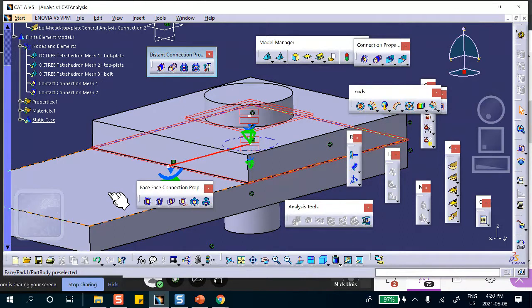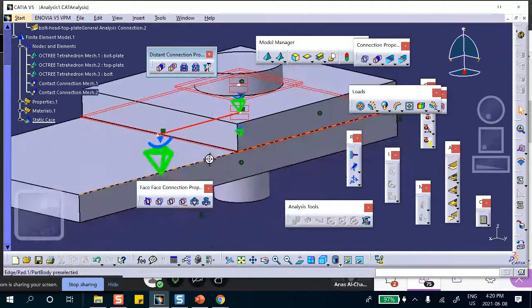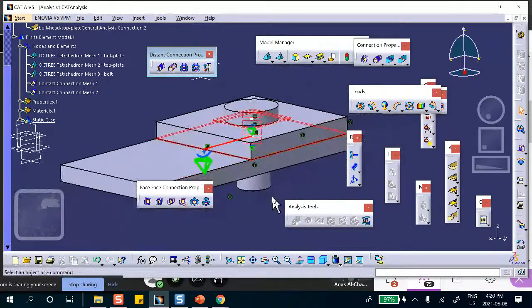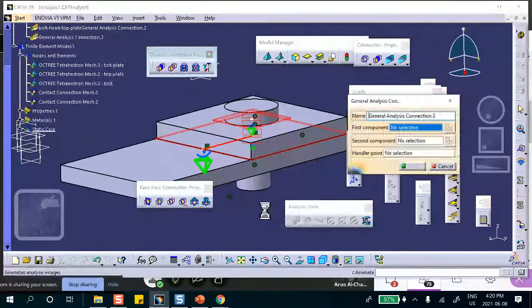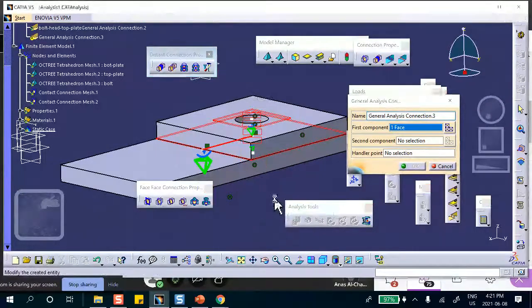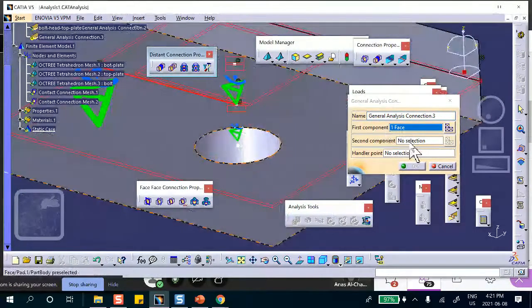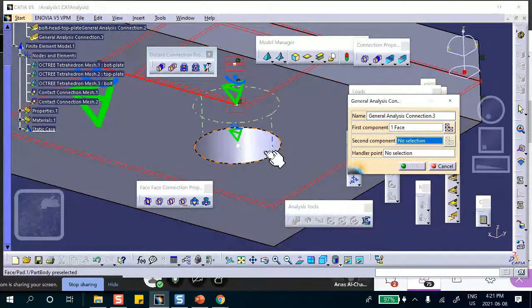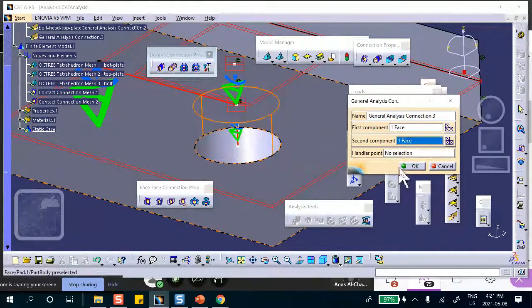Is it the top hole or the bottom hole? Bottom. Yes. Correct. Very good. You can put it in the top one, but it's not going to do anything. Excellent. So here's what we're going to do. We create a connection between the shank of the bolt right there, first component, and then hide this. And for the second component, the connection, because we're going to be using a bolt, is in the bottom hole.